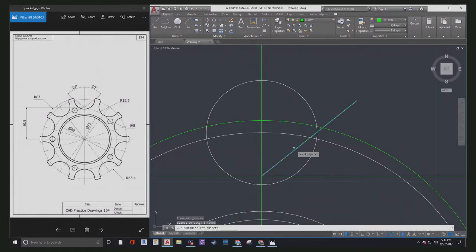So I'm going to click on my object, enter, and then snap, and snap. Erase source objects, no, I want to keep it. And then now I have my chamfer that clips out. I'm going to turn these lines, instead of guidelines, into my solid object lines. And I'm ready to trim. So I'm going to use this outside circle and trim that. I'm going to then also do trim. I'm going to use this circle to trim inside.